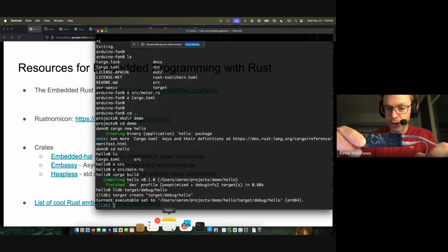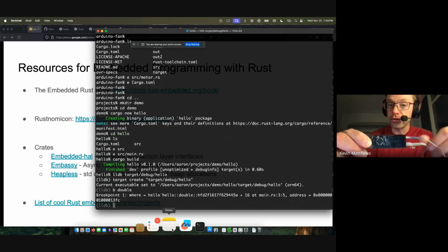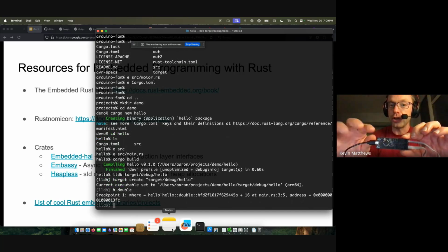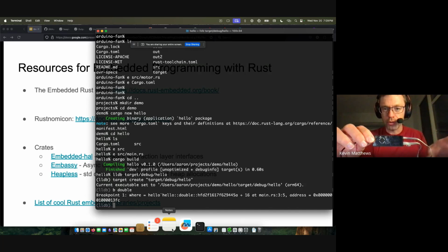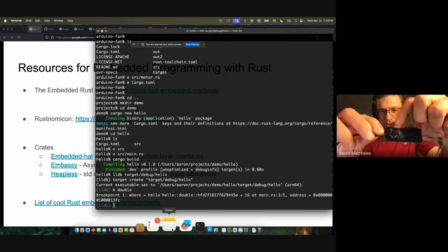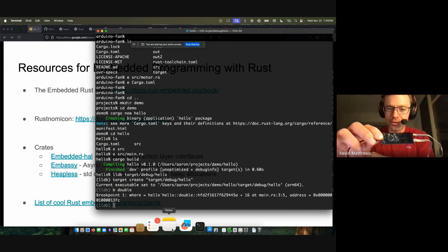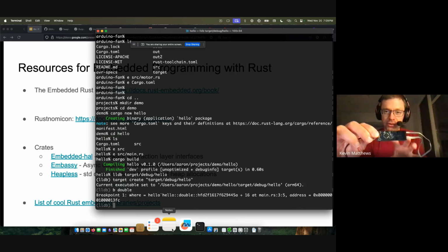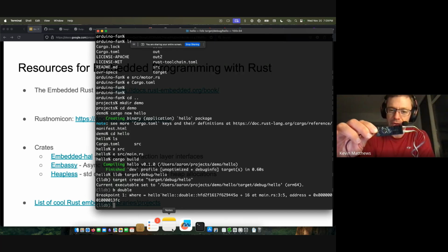And then this bigger ribbon cable is a 10-pin that's a JTAG interface. So you can use this to plug to a little circuit board that's Espressif specific. And you have to use this particular dongle that knows some of the details of how to connect to it. So you'll see a similar thing manufactured for each different chip manufacturer. They have their own tools and often their own specific hardware.